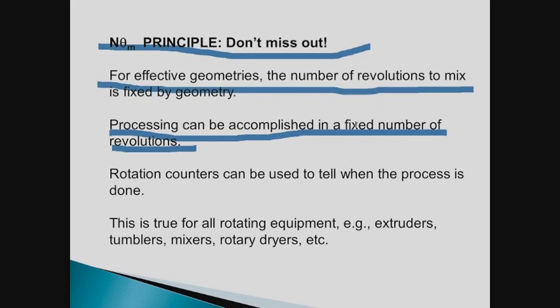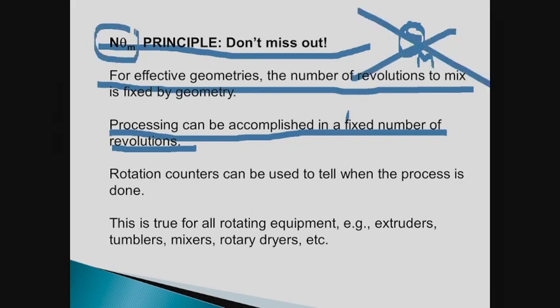So you've got to stop and think about mixing time, right? This n theta, the mixing time is not important. It's the n theta that's important, right? It's the n theta that's important. This is also true for a lot of rotating equipment. This is something you can take home and bank on.